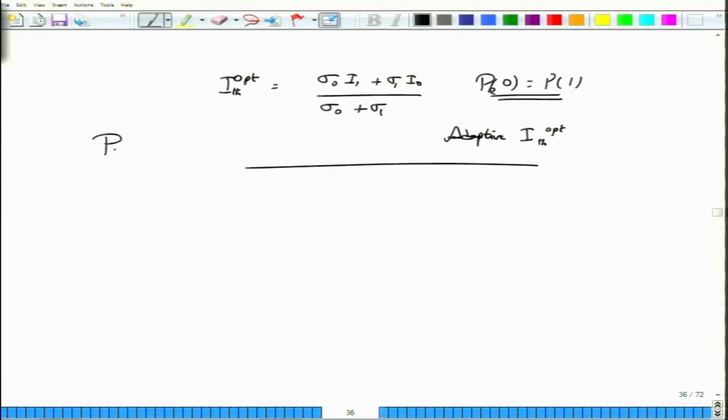It is also common, instead of talking about BER, to ask what is the minimum signal that one needs to transmit when you launch a bit 1, because usually again bit 0 does not really give you much of an error, or the extinction ratio is reasonably high, sigma 0 is reasonably small. So, in comparison to sigma 1, you do not normally worry about that, but as you start reducing the optical power, then thermal noise will also matter. But in any case you normally ask for what is the average power for bit 1 such that a given value of BER is maintained, and this minimum received value is what is called the sensitivity of the receiver,